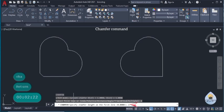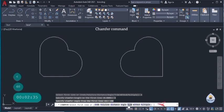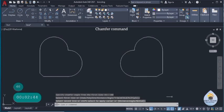I press 1, enter. Then it's asking for the angle. I press shift, then the less than sign on the keyboard, then let's say 60 degrees. Then I click enter. It says to select the first line, so between this line and this line. So this is it, at 60 degrees. That is how you can use your chamfer.